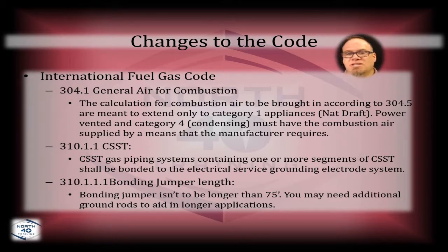310.1.1 dealing with CSST: CSST gas piping systems containing one or more segments of CSST shall be bonded to the electrical service grounding electrode system.